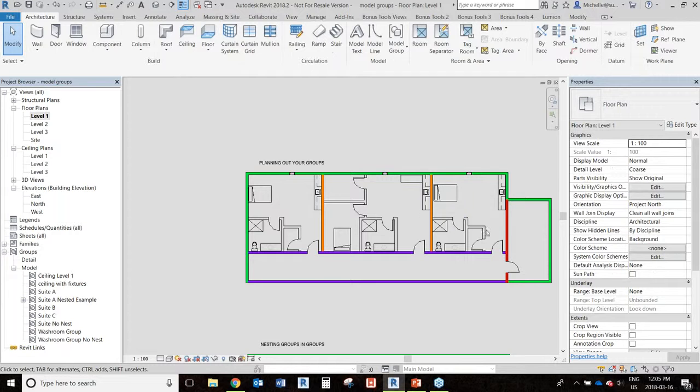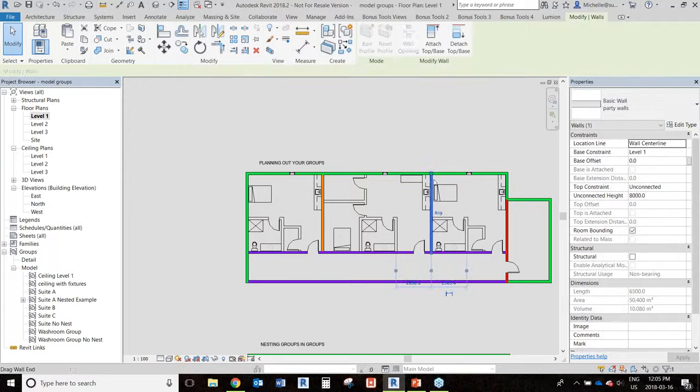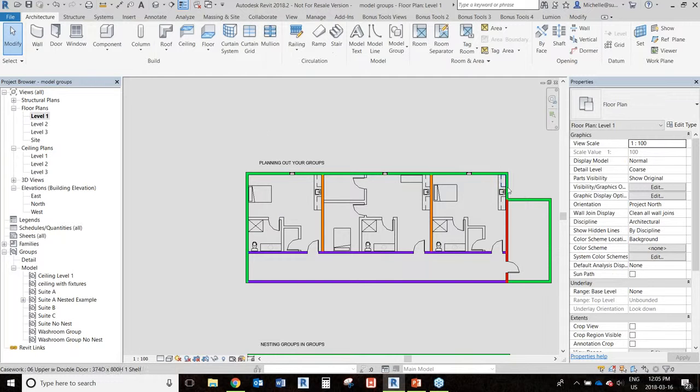So for example, if you take a look at this group here, that's the same as this one over here, we have different wall conditions. So you have a group that has a party wall on one side, you have another one that has an exterior wall. Over here, you might have exterior mixed with a stair. So it might have seemed really simple at the beginning of design when you just are blocking out portions, but when you start to put more detail into your project, you'll start to notice that now, oh, do I have to duplicate this group because I have a different wall situation? And that can start to get a little bit confusing. So that's why I generally like to have those outside.